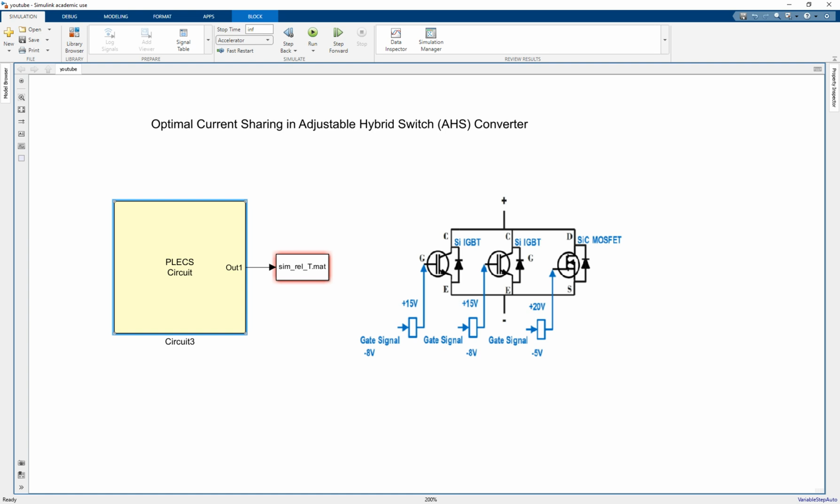Because what I'm looking for is the power loss, switching loss, and conduction loss. These are actually a little bit complicated because they all depend on the operating point, the temperature of the device, and also solving the circuit, KVL, KCL, finding out the IV curves, and also the switching loss. Also, that one depends on many factors. So I trusted Plecs for this kind of calculation, calculating the power losses.